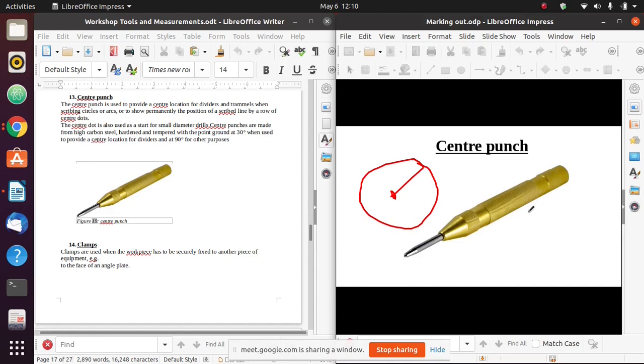So we hold this part with our hand, and then we place it where we want the center of our circle to be, and then we hit the head with a hammer, and a point will be inscribed by the sharp edge of the punch. Now we can also use it to identify the center, the start point of drilling.